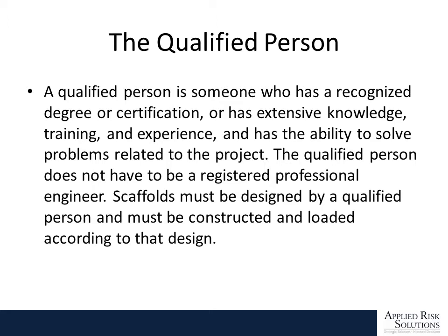A qualified person doesn't necessarily have to be a registered professional engineer, but scaffolds must be designed by a qualified person and must be constructed and loaded according to that design. So a qualified person has to be able to work all of the statics and strengths and be able to design the project so that it's going to be safe for not only the erectors but also the people that will be using it.